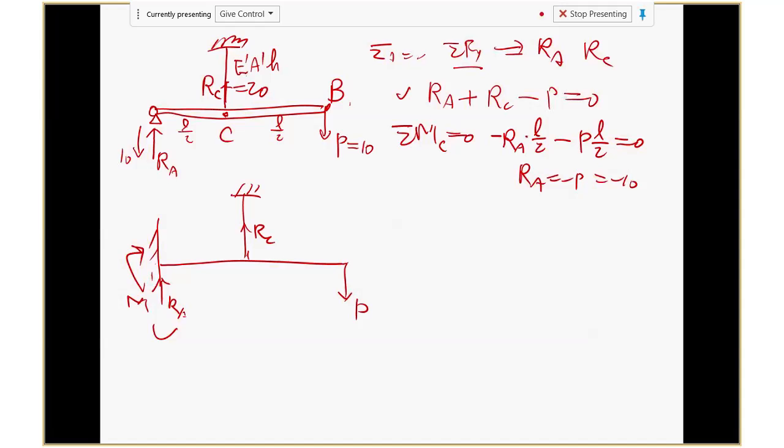When you have this beam there, right? Now imagine you're pulling here. This point is going to move down, right? Why is this point moving down? What causes it to move down? The force. Okay, why does the force cause it to move down? Because you have a beam here. The beam is going to bend. So that bending will make it move down.